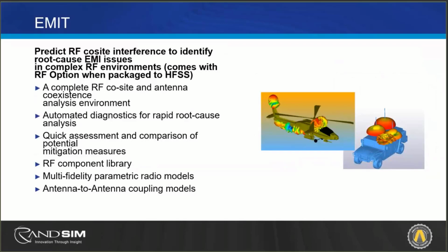This is a tool that you can include where you can analyze and investigate your EMI issues in the pictures we show. Co-site could be potential co-site issues due to multiple antennas. It can be desense due to having high-speed lines and an antenna on a PCB.